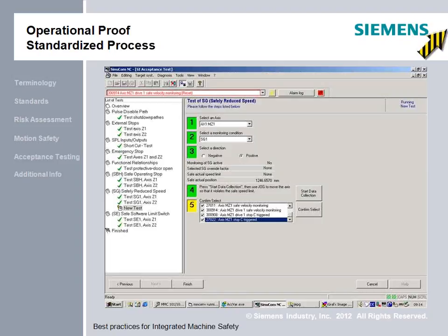In this case, I'm showing a Sinumerik Safety CNC acceptance test, and Siemens has a semi-automated wizard that helps with this process, but the concept is similar across all the safety systems where we must test and document the implementation. Historically, if I have a safety relay and an emergency stop and a contactor, my safety system checkout was a checklist and a meter in my back pocket, and I would press the e-stop, I would listen for the relay, I would check voltages, make sure the contactor changed state, and that was my test.